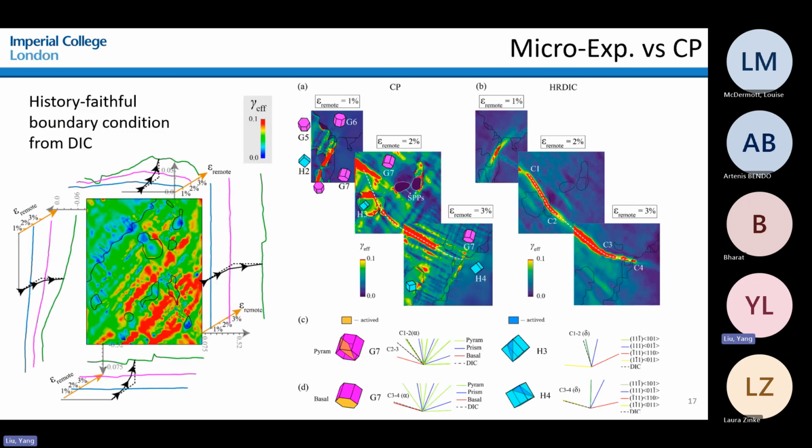So by applying the same technique, which is crystal plasticity again, we begin to understand the behavior a bit better, where the slip actually transfers from the matrix to the hydrides, and then transfers out as well to the matrix. So there are complex interactions between the hydrides and the matrix involving these slip activation mechanisms in both matrix and the hydrides.